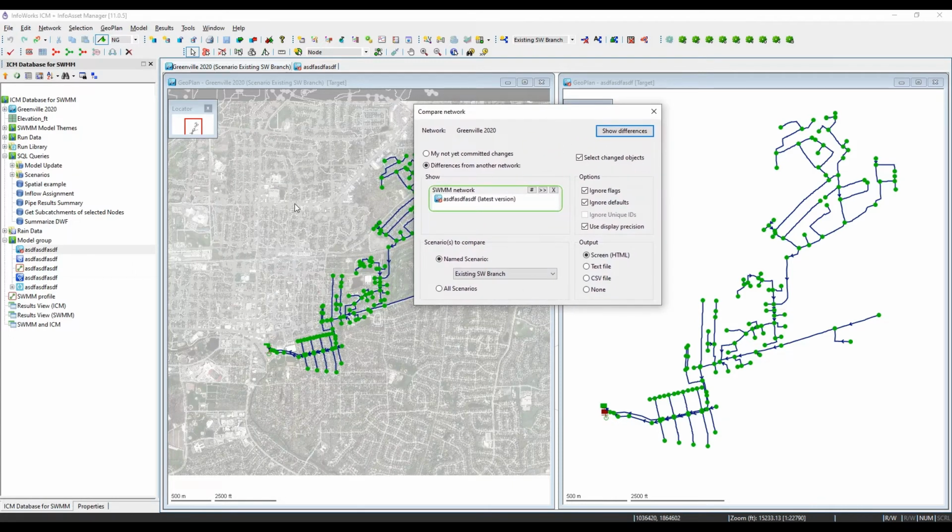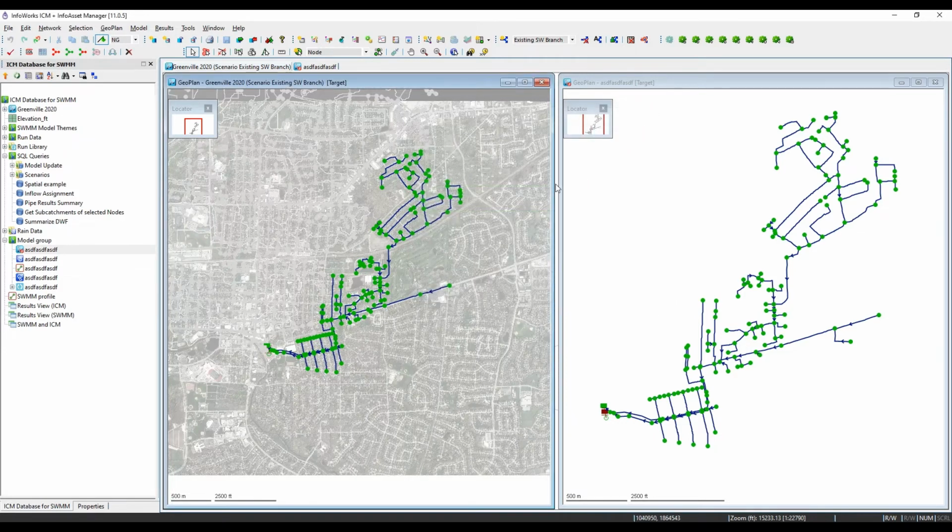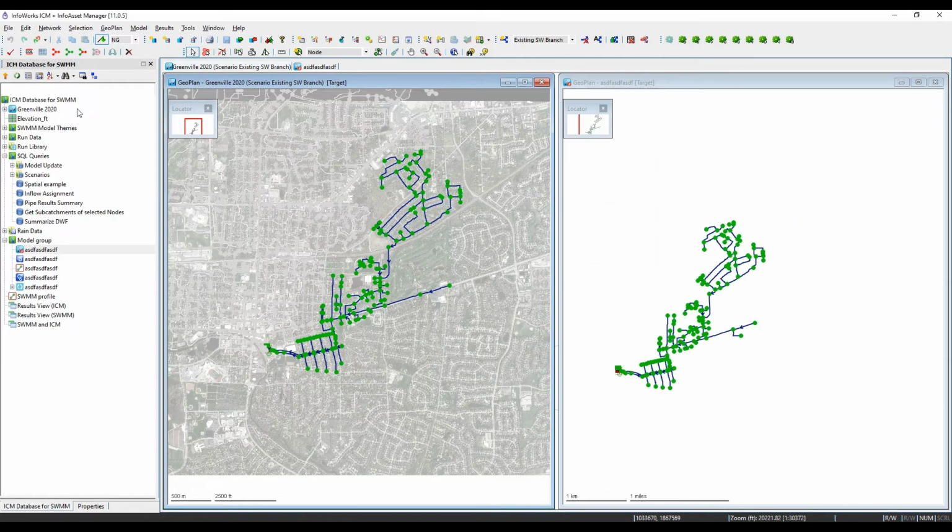So in general, if you do happen to have multiple versions that people are splitting off and working within ICM, this is the approach, and you can actually push the changes to a CSV file where you can then manually review and filter out, and you can actually then update a model from that same exact CSV in that right format, and then it will bring in those filtered out changes into your updated model. But we're not able to do that in this case. So I'm going to show an alternative approach. Because I like using SQL queries.